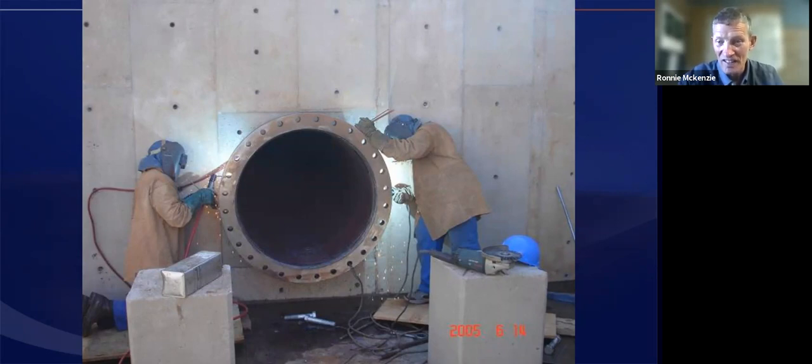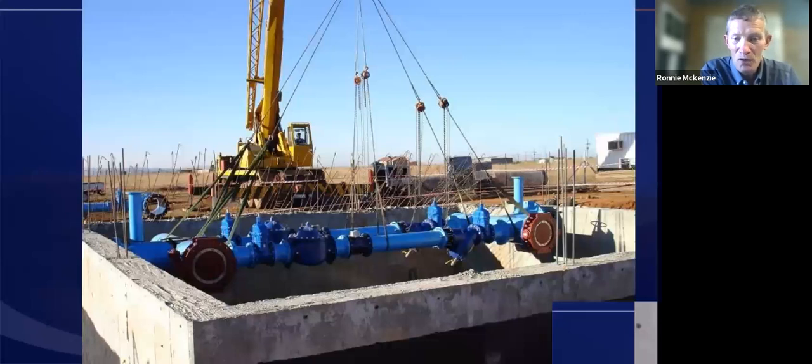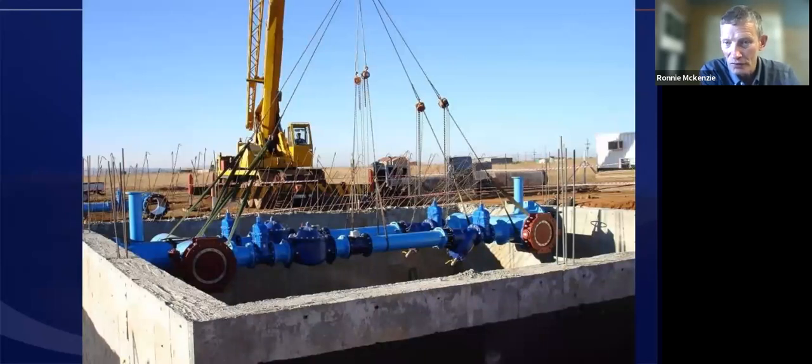So make sure you test it before you cut the pipe. Make sure you can shut the water off. That's a good pointer. You use a big flange plate because the pipe will not be round. You've got to bash it back into a round shape and then weld the flange plate on. You want to pressure test all your valves and things before you put it in the installation.